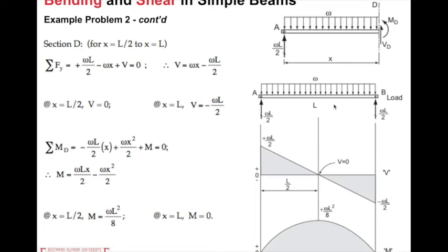So you can find that for uniform distributed loads, the curve is more difficult than for the concentrated load. When we calculate the shear V and the moment in simple beams with concentrated loads, we need to make a cross-section cut between every two neighboring concentrated loads.